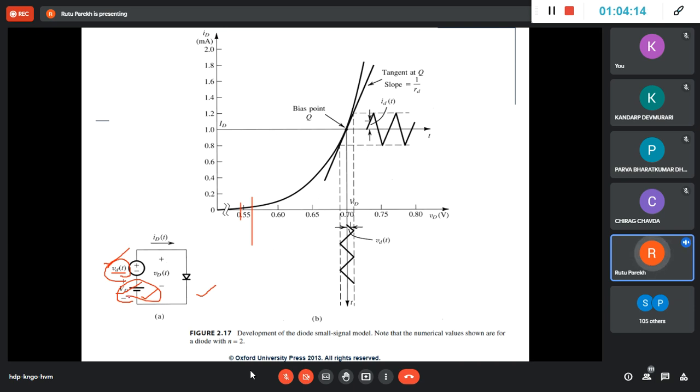But when you are processing a signal, in signal processing, the signals are weak. They are of the order of millivolts. If you give that signal directly to the diode and you think it will rectify, no. You give enough energy to the diode first if the signal is weak, and that is biasing. Understood?